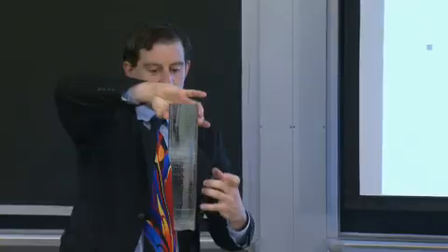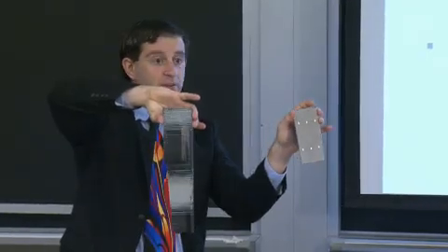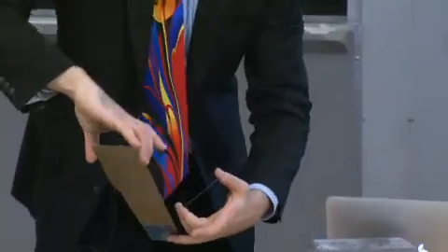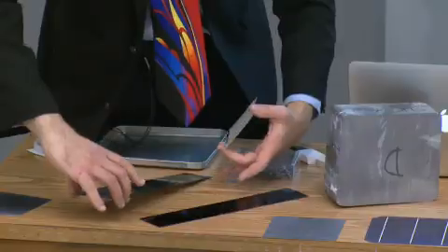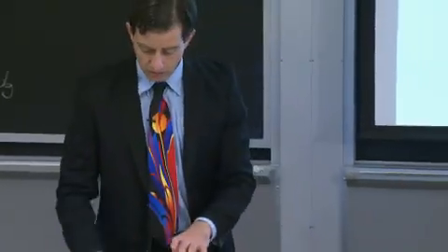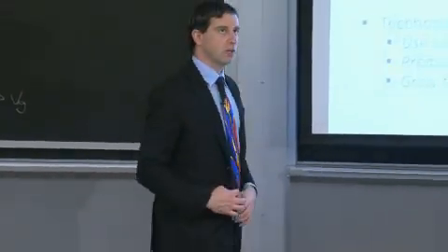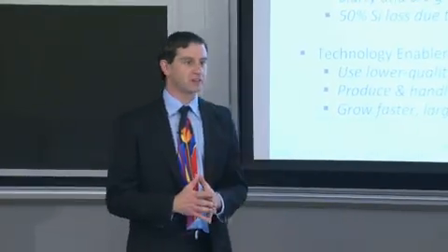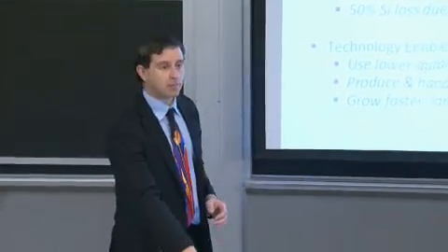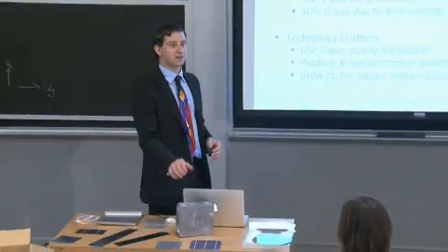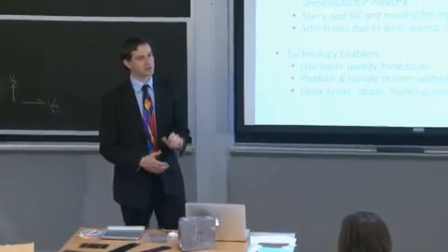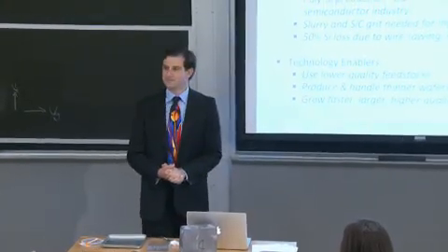If you look at the total height, the wafer is around 15 centimeters long, and the laser cut itself is something on the order of maybe, I'm going to guess, a few tens of microns, maybe 100 microns in that order. And so the amount of kerf loss in that regard would be 100 microns over 15 centimeters. So a relatively insignificant fraction. If you were trying to chop up this using a laser, yes, then you would have significant losses. But since you're growing that ribbon straight out of the melt, the laser cuts themselves are a very small fraction of the total silicon.